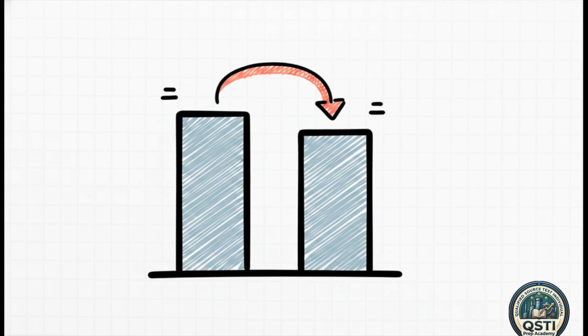But wait, the EPA actually gives us a much simpler alternative calculation, known as equation 3-2. Instead of messing around with confidence coefficients, this equation just takes the absolute value of the average reference method minus the average CEMS value. Super straightforward. It's just the strict difference between the two averages. And as we're going to see in just a second, you can actually use this simpler equation to pass the test under some very specific conditions.